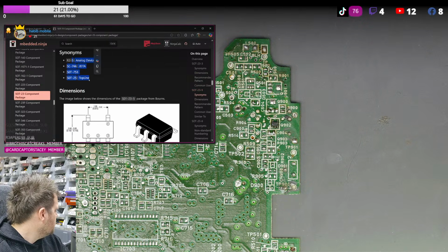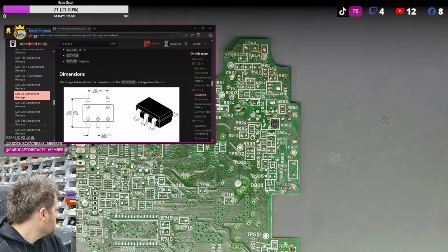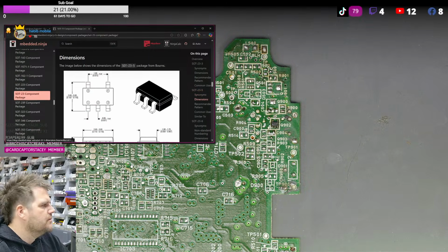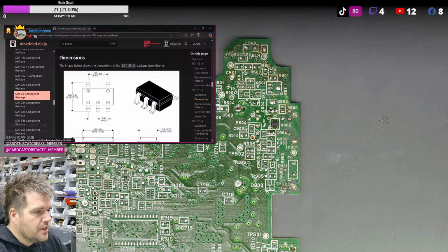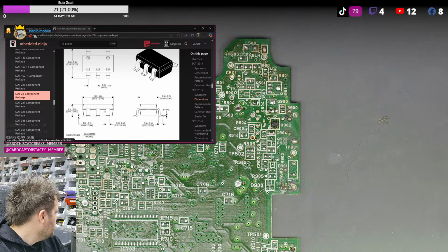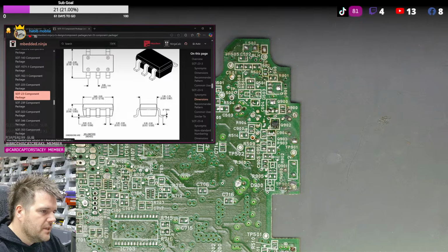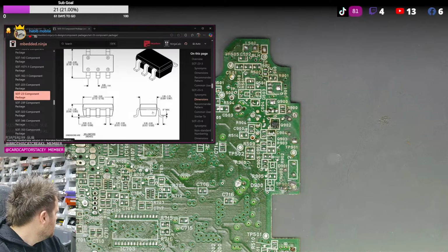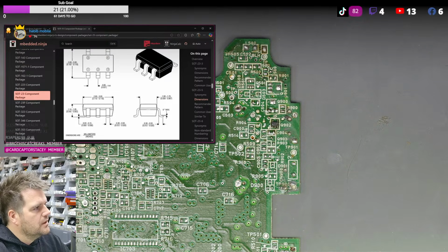Alternate names of the packages, because you can have various names. And then this is what we're interested in. So now you can see there's a width here of 0.95, so almost 1mm. So that's our vernier measurement, very much likely, just slightly out. So that adds up. So then let's measure the package, 2.8mm. Now you remember we measured 2.9, so that's the width of the actual black body. So the final confirmation is just the width or the length, whichever one a class does. The other dimension is 1.5 millimeter.